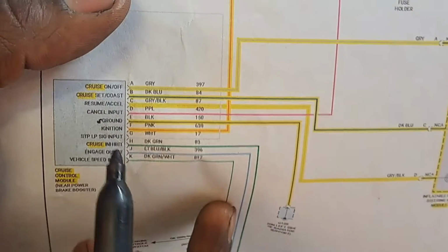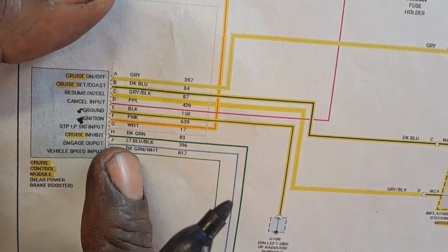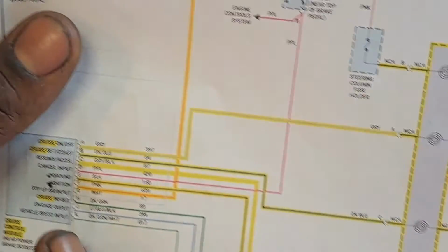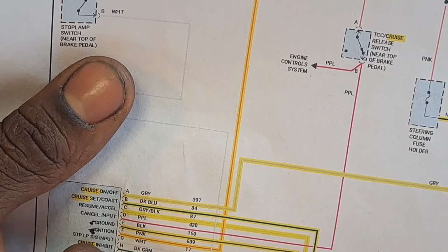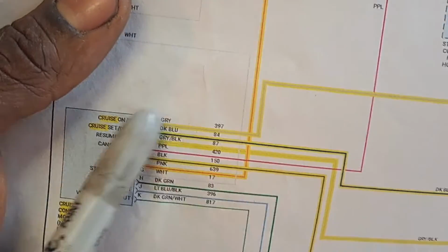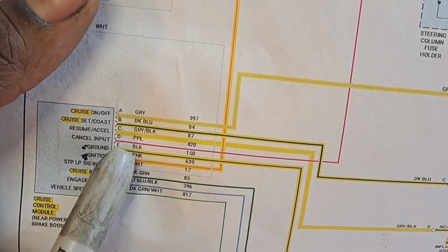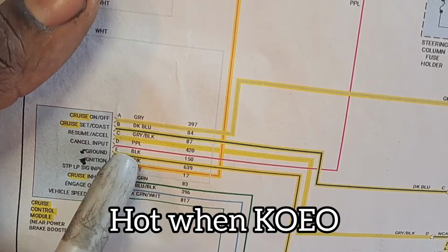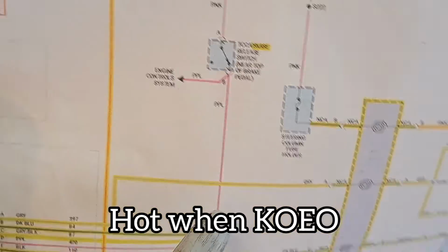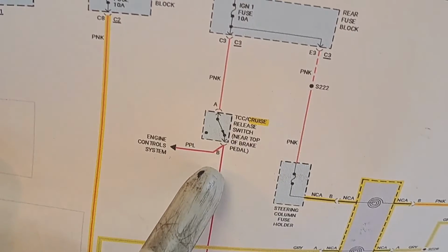So we checked our power going to the ignition. There's another power source here. Next we're going to check the cancel input right down at the bottom. This is going to be D, the purple wire. Now this runs all the way to the brake pedal. From what it looks like, the static state is a constant 12-volt source.